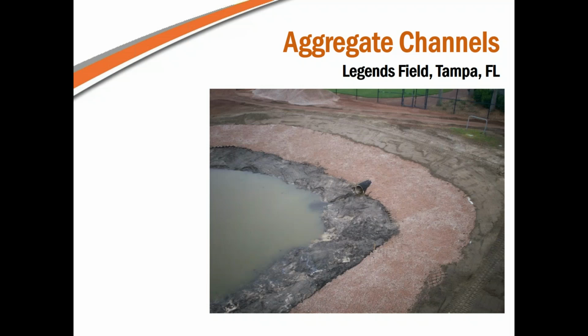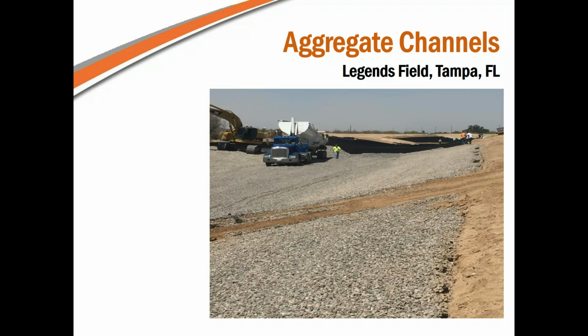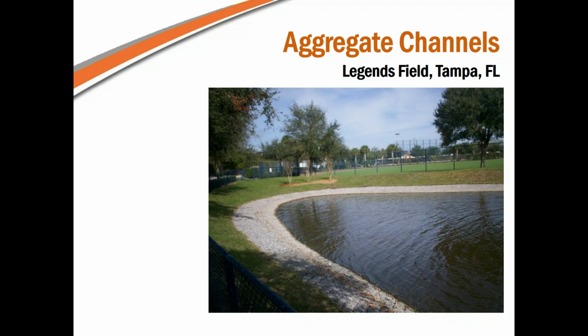Panels are easily cut, as can be seen here, so the sites can be customized to your specific needs and regulations. It's also good to note that heavy trucks and construction equipment can drive on the GEOWEB areas immediately after infilling as an access road for construction, even all the way up. This way you can limit the amount of excavation or temporary buildup on sites because you don't need additional access roads when you can simply drive on the GEOWEB system.